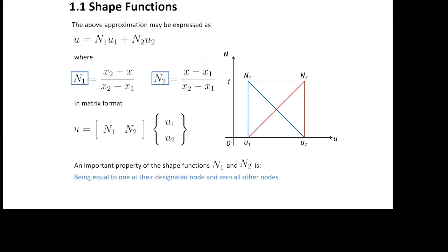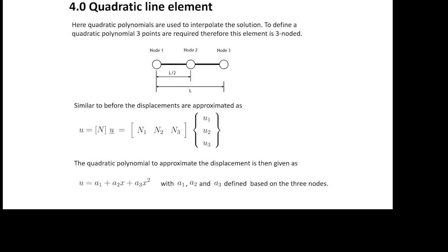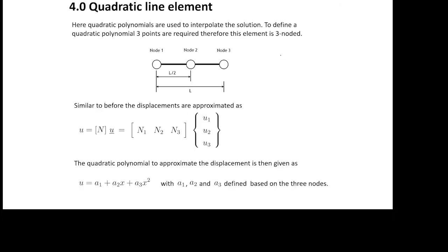And this is why we are going to use quadratic elements. So what we are going to discuss today is quadratic elements. So this type of elements. Obviously, before we had u is equal to ax plus b. So our element had two nodes. When we're talking about u is equal to ax squared plus bx plus c, we have three unknowns. So we should be talking now about three nodes. So it is not a two-noded element anymore. It should be a three-noded element.